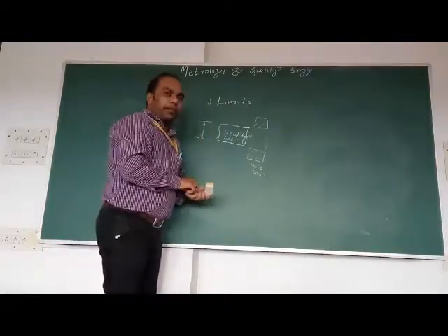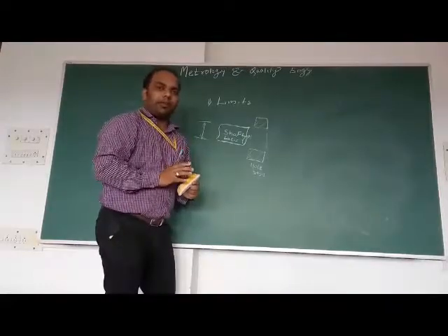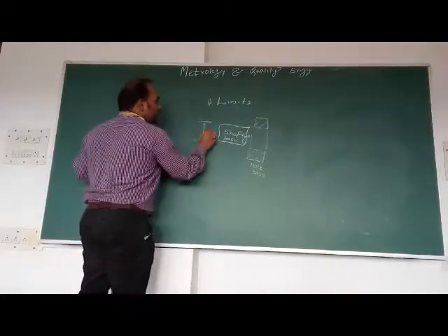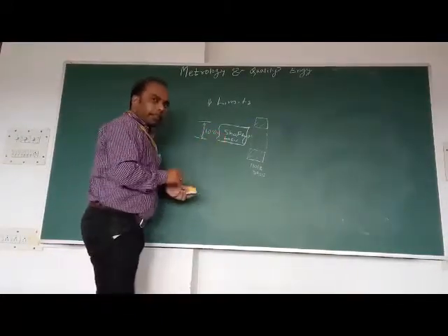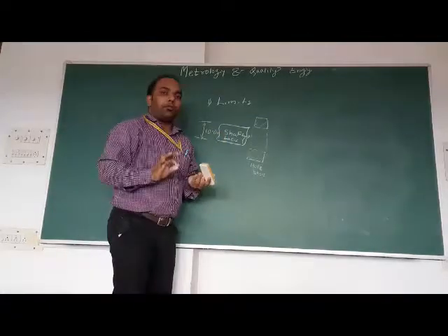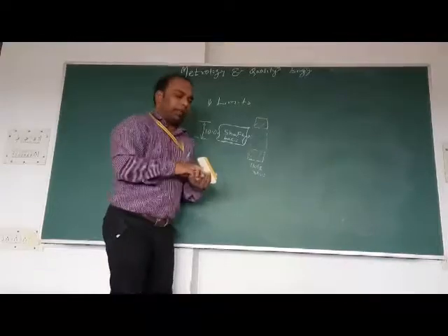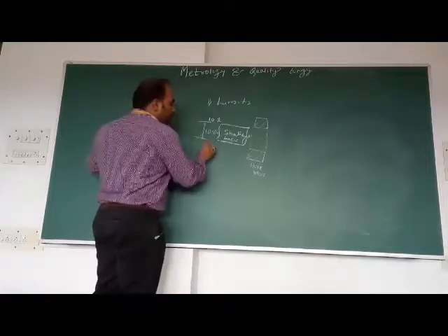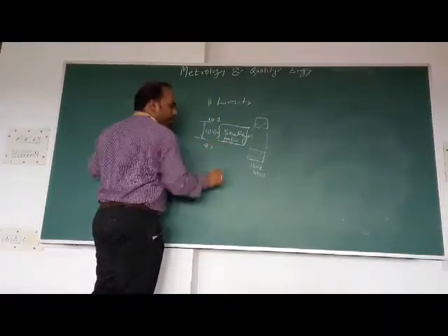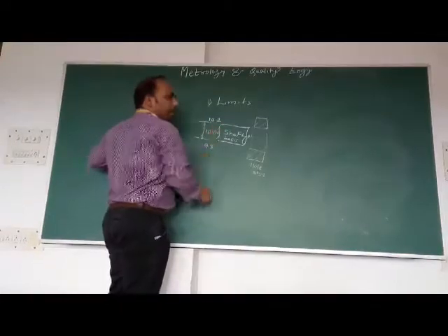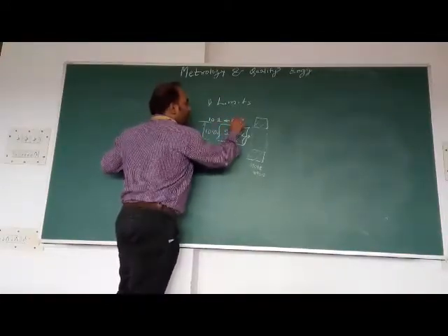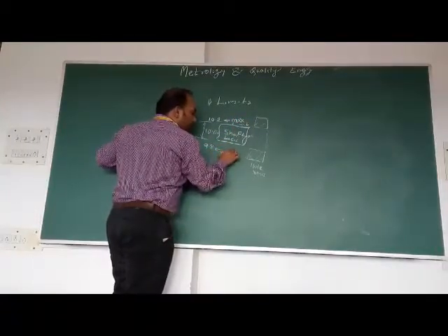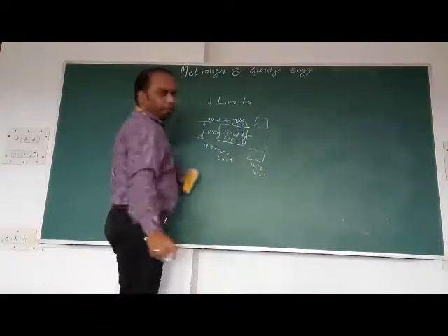Now, what type of limit does the shaft basis system have, and what type of limit does the hole system have? Let us understand. For the shaft basis system, the basic size is 10.00 centimeter. If the component goes up to 10.2 and may reduce its diameter down to 9.8, then these two are the limits, called the maximum limit and the minimum limit for the shaft basis system.